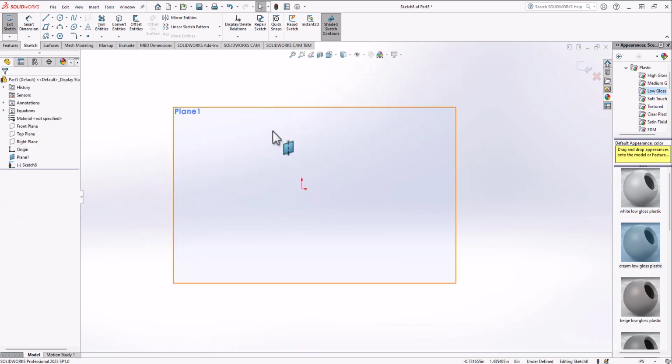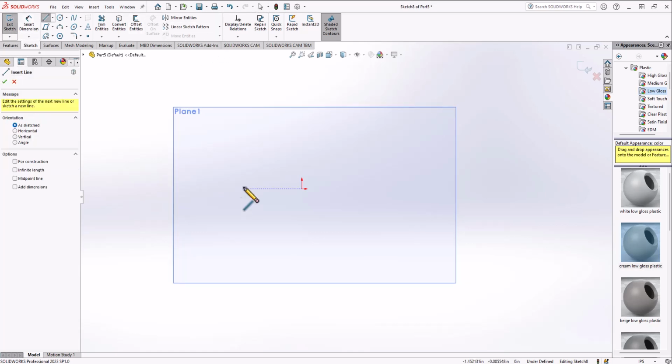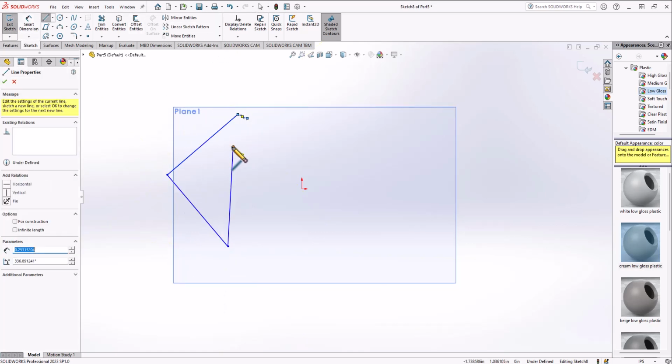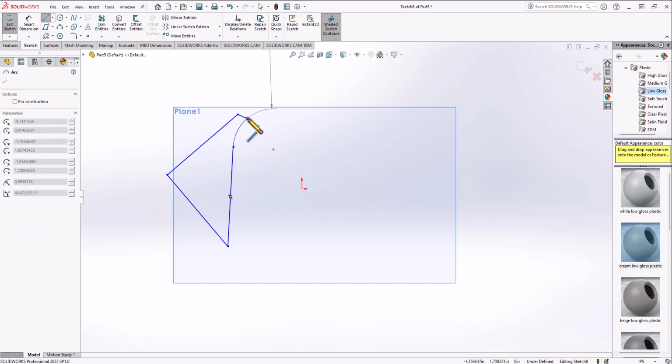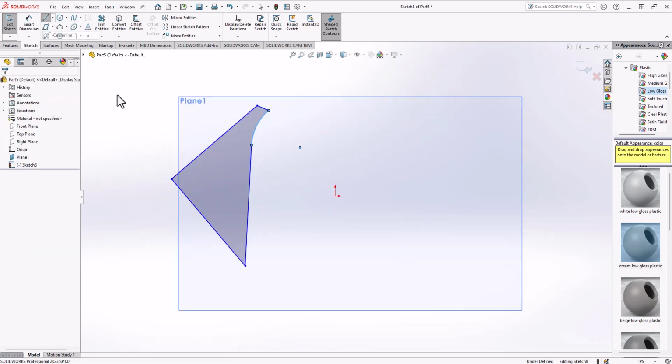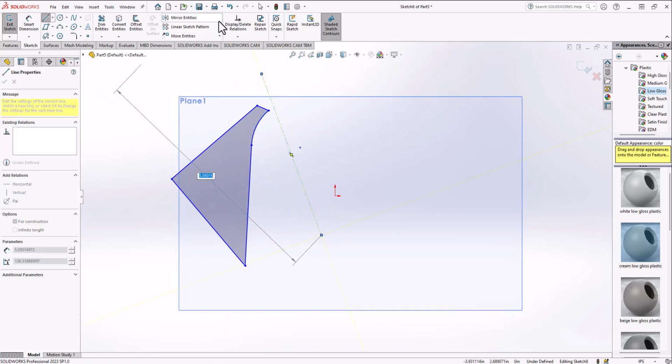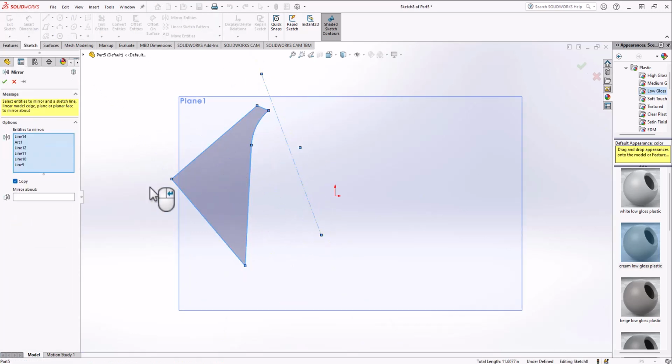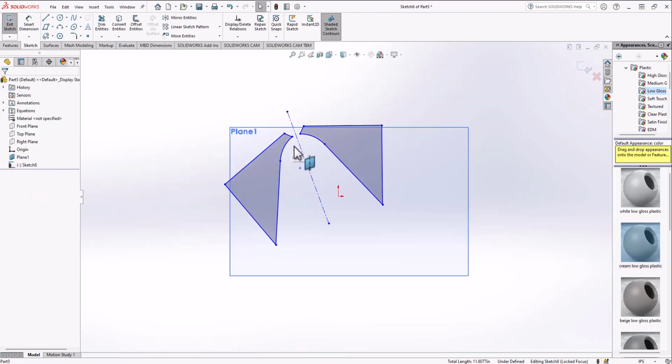All right, so you've got the move, copy, all those. You can also do, say I have another complex geometry, like that, and I want it to be on both sides of some line. So I can draw a line, and then I can just hit mirror. I can click on the entity I want to mirror, and I can click the line to mirror it about. So now I can make two of them that are mirrored from one another.